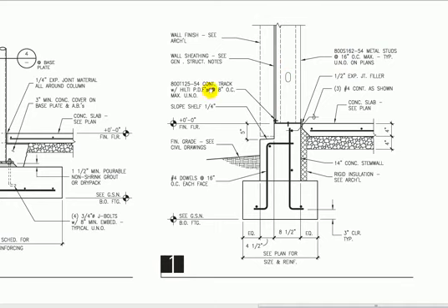And this tells us a little track to put down, and then the specifications and notes will tell how to fasten them together. On structural concrete drawings, these heavy lines indicate rebar. The size of the hooks are usually not shown because those are standard per ACI specs. So a standard 90-degree hook is what the contractor would give there unless there's a dimension shown. A circle indicates a rebar that we're cutting through, so those are longitudinal ones. So you can see in this wall, you can see this line here.